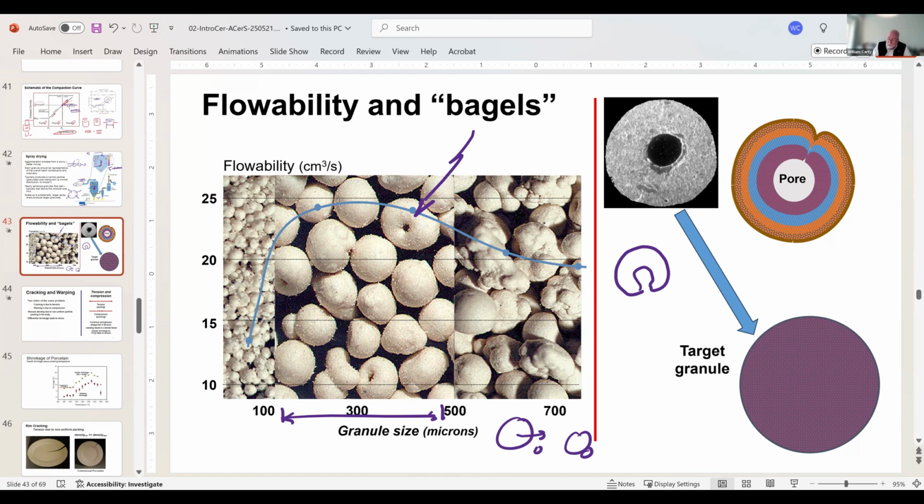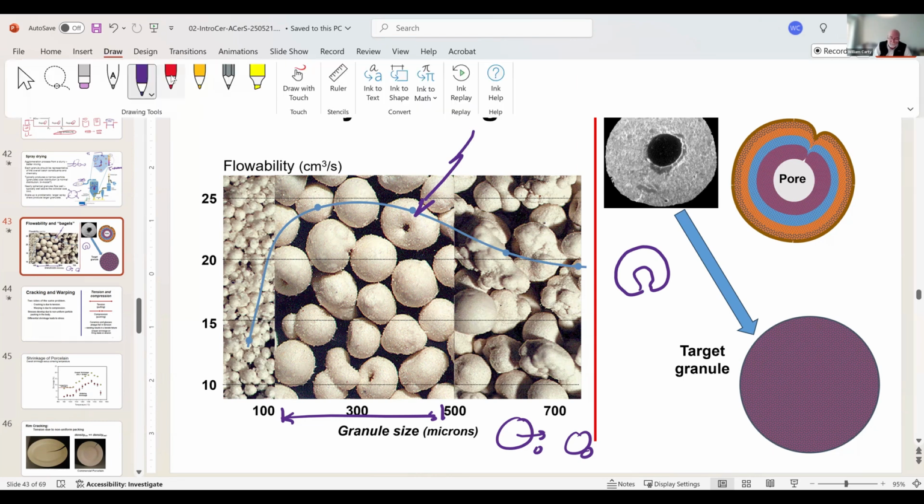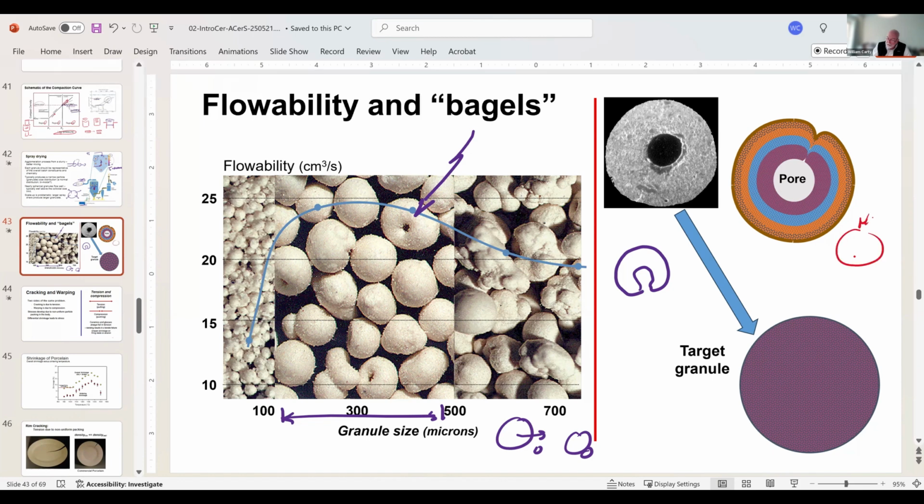So this droplet in the spray dryer, okay, is warmer at top, hot, and cool, okay? So you get a thicker layer on the top of a dried material because it's drying quickly, and a thinner layer on the bottom with a liquid jelly center, if you will, and this ruptures, okay, to provide an opening. So that's what happens. And then you end up with this.